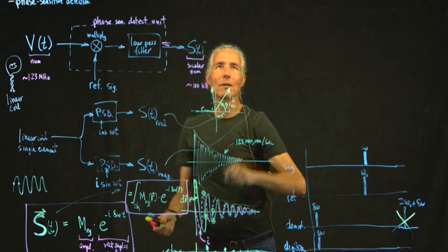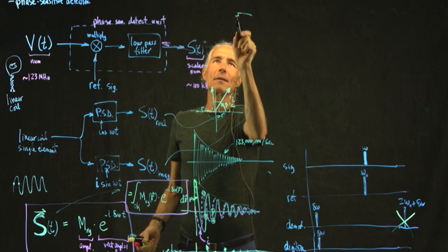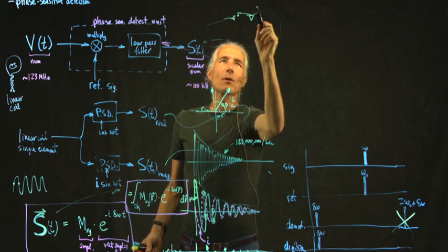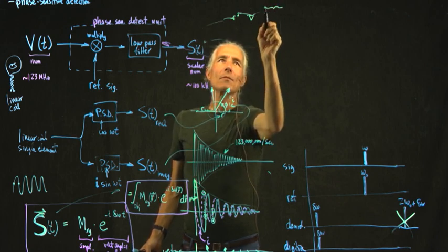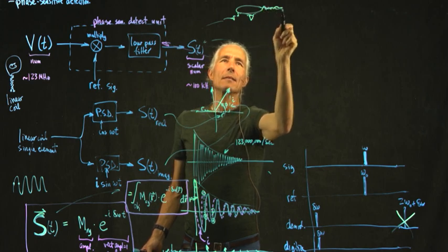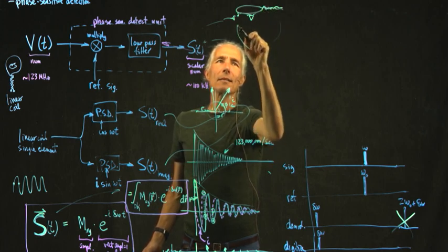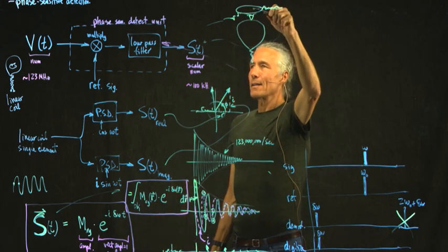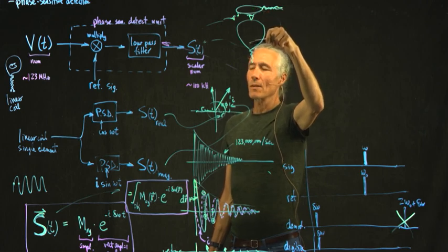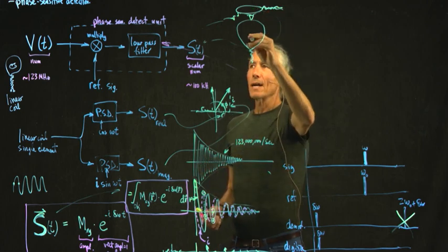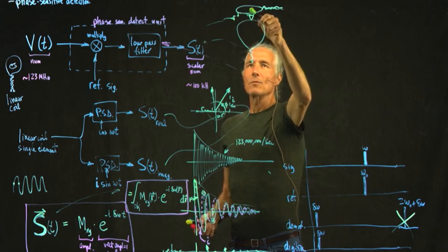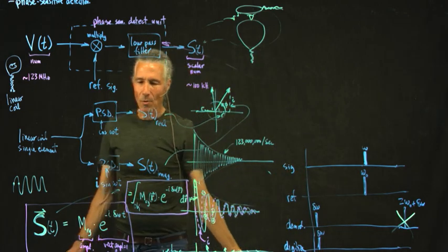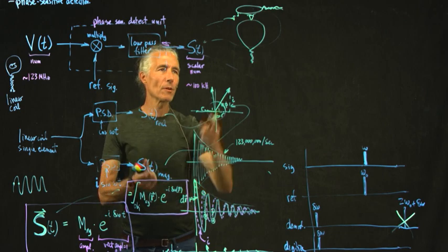So you've got a head here, and why don't we just put a coil over the head like this, and then put a sideways coil like this. This one would record the sine, and this one would record the cosine. If you put an oscillating thing in there, these two would be out of phase by a quarter of a cycle, and that's basically a quadrature coil.